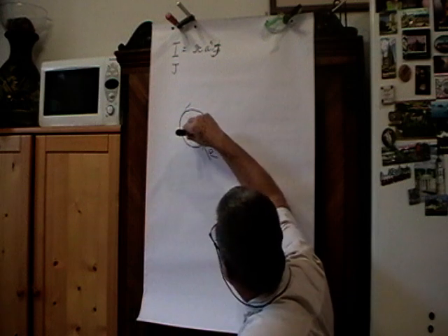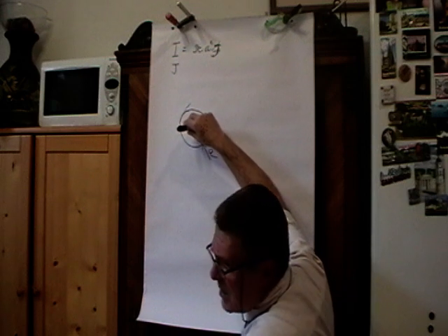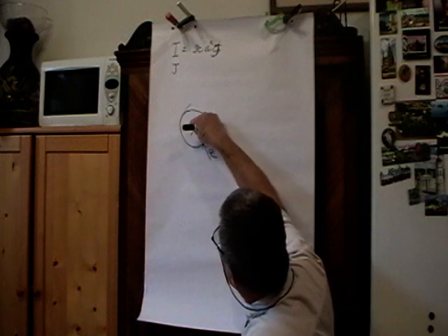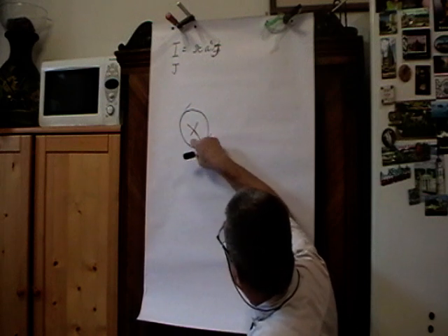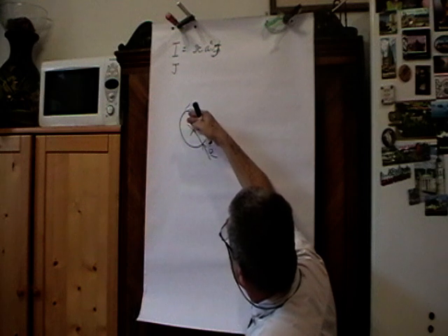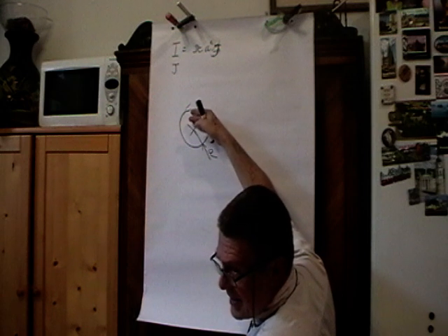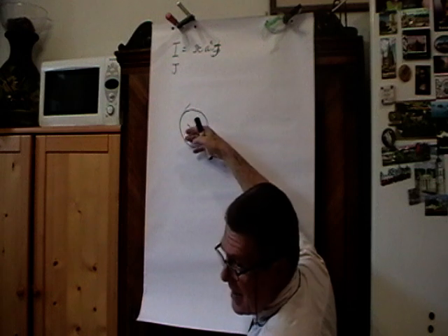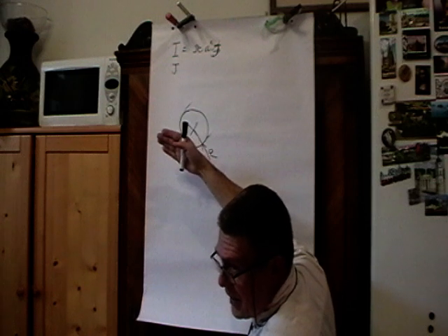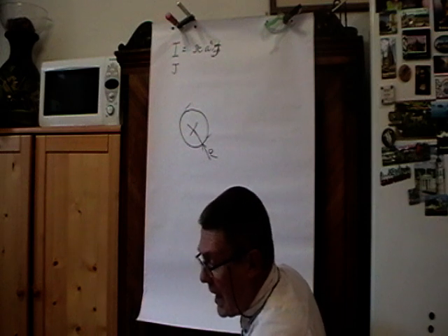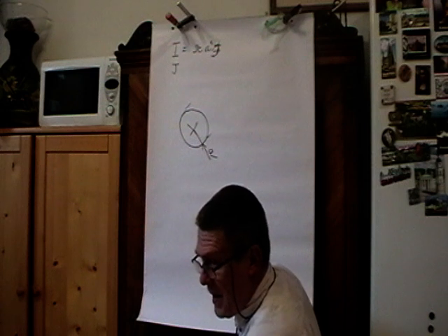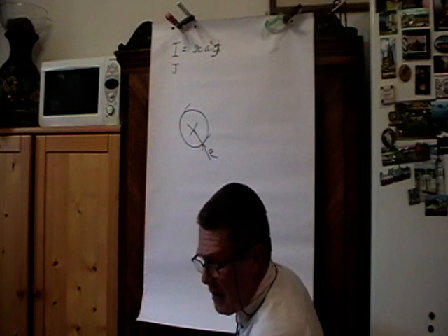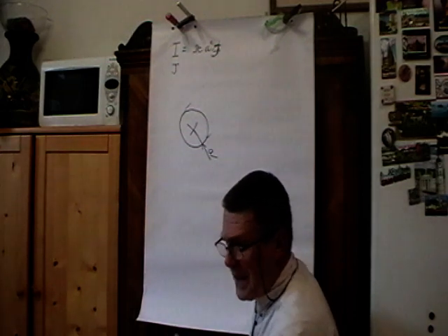Due to the fact that there is some current inside, let's say at the middle of the conductor, we would have a magnetic field that makes circles around it. The field lines would be circular, and you will get those lines inside the conductor, and this flux will account for some inductance. Now we would be happy to use the same equation as we did, the static definition, but there is a trouble with it. I mean, the definition holds, but we will not be able to use it. I will show you why.